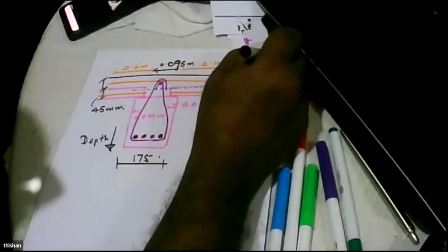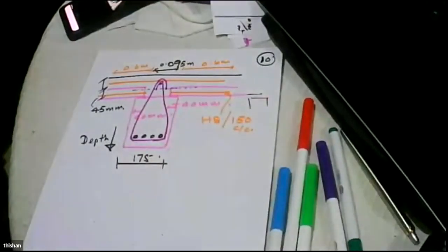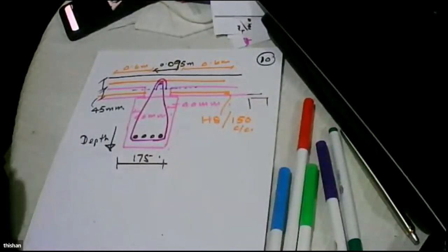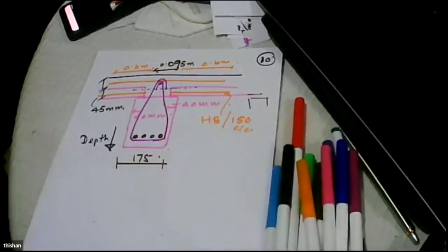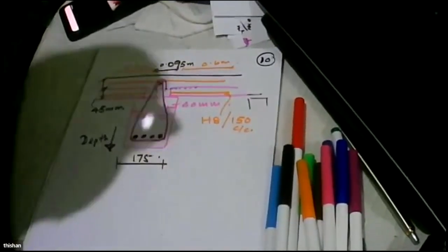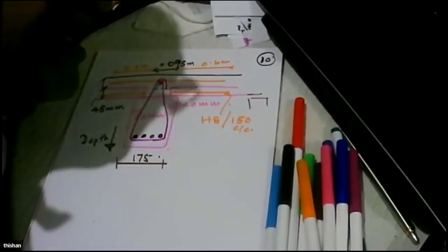So generally when you have a 90 millimeter slab over 2 meters, shear will be minute. You don't have to worry about shear. Is that clear? Yes, yes, sir. Then shall we take the questions?